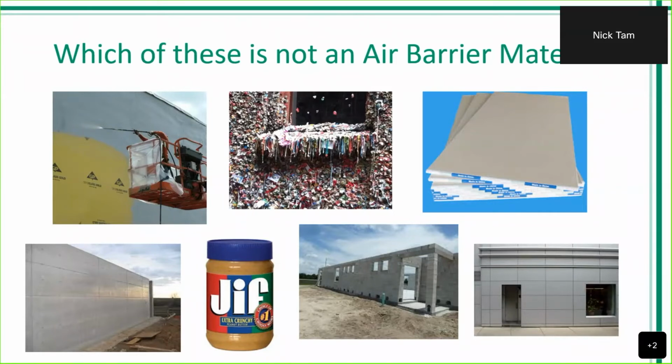But what they're not going to take into account really is, is it going to have waterproofing capabilities? Is it going to have those tensile strengths or elongation factors? Is it going to have flexibility and good recovery should the building move, contract, or expand? Also, we think about UV exposure. Every product has a limit, and some of these products may not be able to be exposed to UV for a long period of time. So the point of this is really just to show that we have to do some good investigation to decide which material is going to be best for our project and not just rely on the code itself.